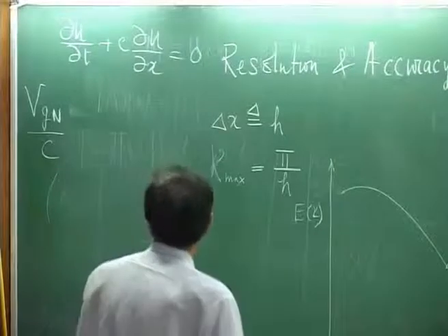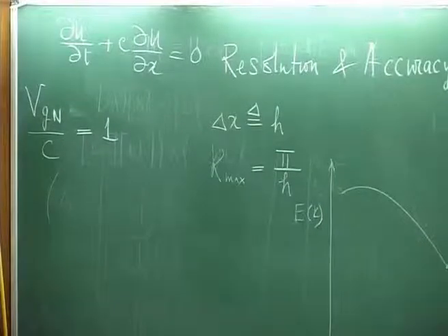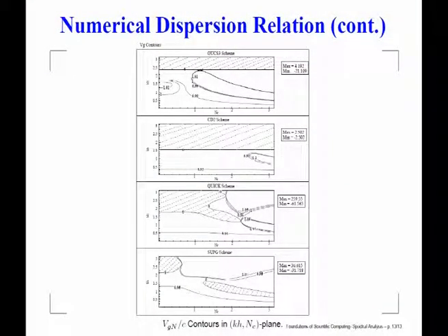So, this ideally should be equal to 1, so that your energy should go at the correct speed as the governing equation suggests. And what you notice in the second frame is that this horizontal line shows about 7% dispersion, that is 0.93 instead of 1. So, whatever delta t I choose, do you realize that I am going to accumulate error quite rapidly if I am here, right.